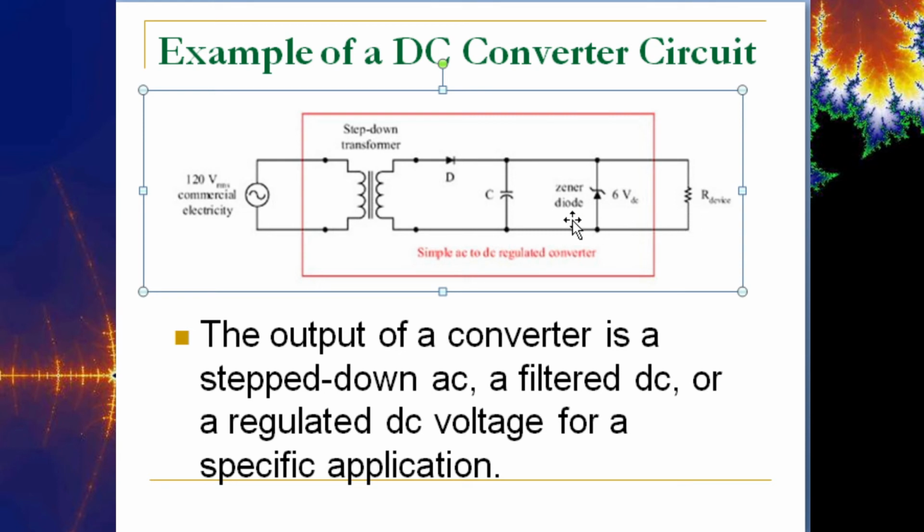Now, if this happens quick enough, you can keep this capacitor charged and get a fairly steady DC out. It's not 100%, but it is fairly regulated. You're still going to get some ripple voltage on the output here. You would want to do some more circuitry, in another more advanced circuits course where you talk about electrical components. There are other electrical components you can put in here, along with a full wave bridge rectifier, which takes 4 diodes, and instead of just blocking the negative half, you would actually turn the negative into a positive.